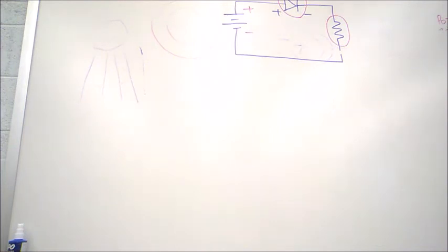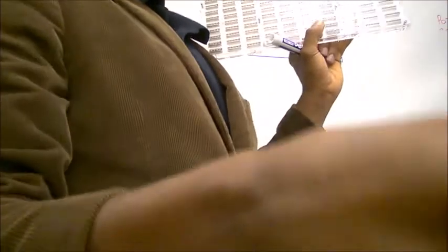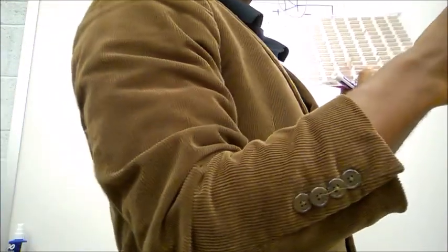So this is the breadboard that we're going to be using, and we use it to make connections. If you notice on your paper on page 4, we have an example of a smaller breadboard. This smaller one is just showing that all of these rows are connected. So if you wanted to connect 2 legs of 2 components, we need to put them in the same row.